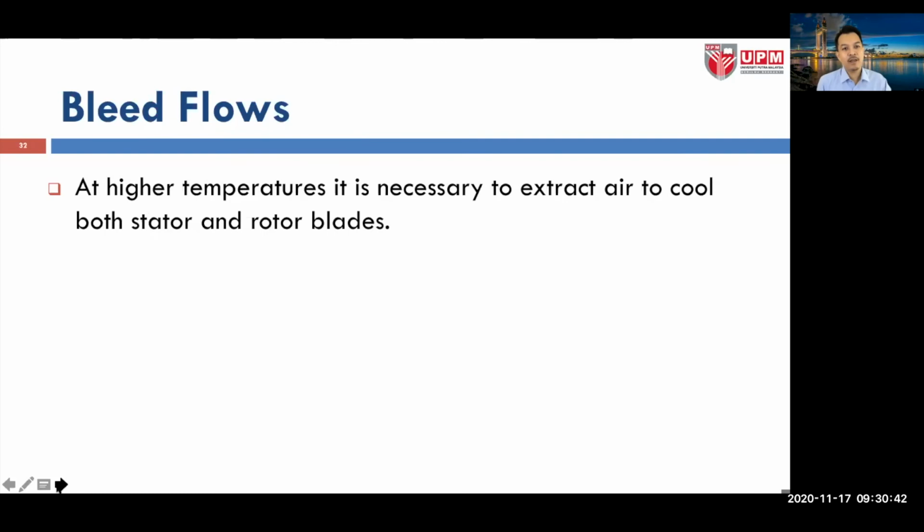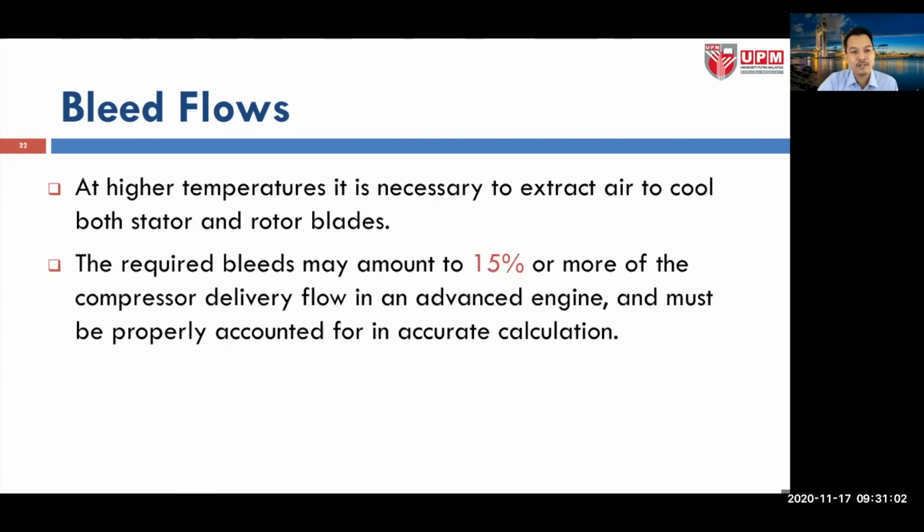As I said just now, at higher temperatures, beyond 1400 degrees Kelvin, it is necessary to extract air to cool both the stator and the rotor blades, because the temperature cannot be withstood by the existing materials of the stator and the rotor blades. So the required bleeds may amount to 15% or more, depending on the type of the engine, from the compressor delivery flow, and must be properly accounted for